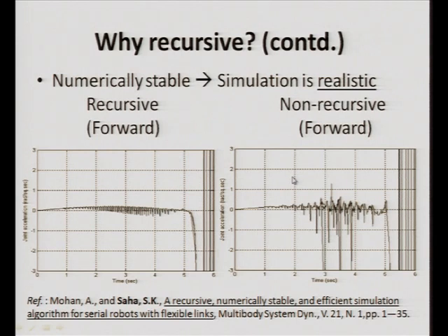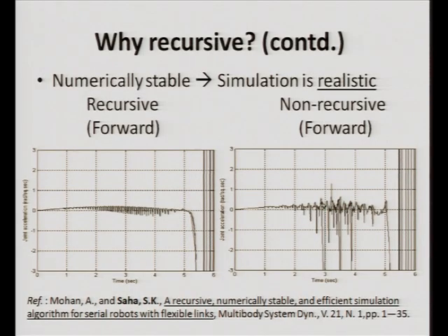Now, to know the motion, we have to integrate. That means from the acceleration we have to get the velocity and the position, which you can finally see in an animated form maybe. Whatever numerical integration scheme you are using, this is relatively smoother than the right-hand side, so the integration results will be relatively better here, which means you will get a more realistic feel. Otherwise, what may happen in a given system is that it may not be unstable, but because of the algorithm you have chosen, it may show that something is changing widely. So your interpretation may be that this is unstable, but actually it may not be.